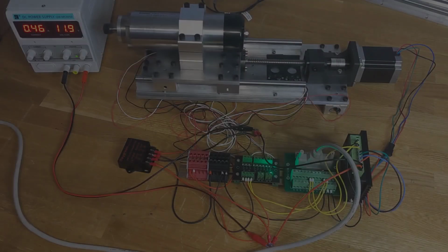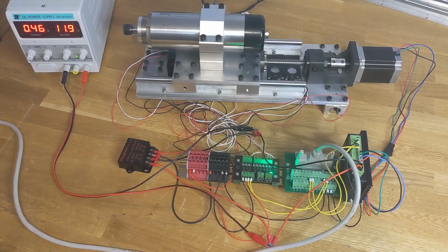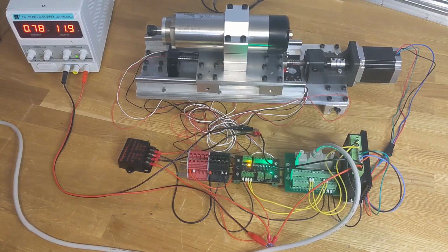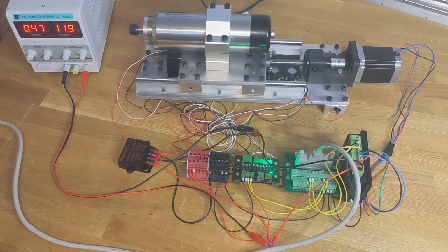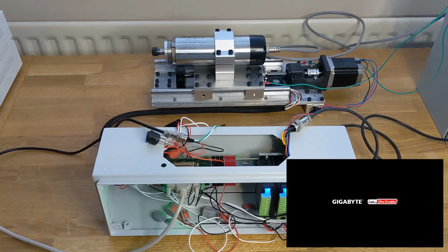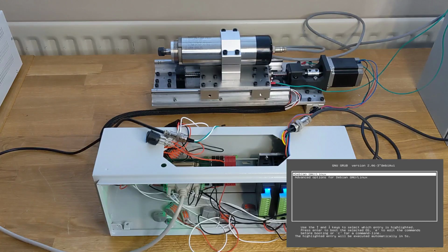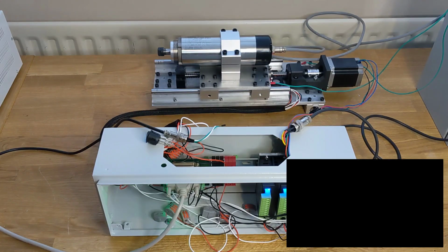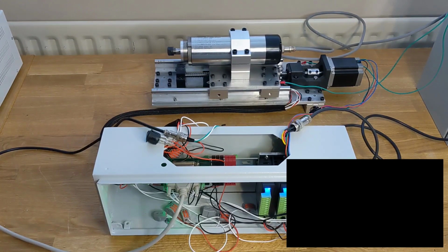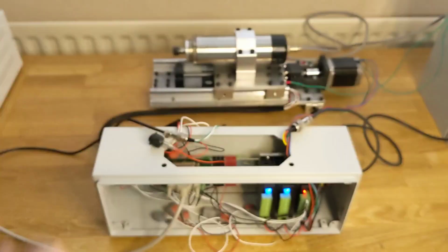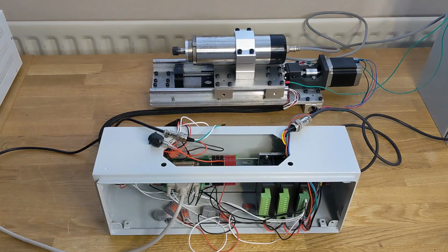In the last video, we set up limits and homing for the LinuxCNC machine. As long as LinuxCNC is in control, then we expect that the machine can't hit its mechanical limits. However, watch what happens when I boot up the computer. Random movements? That's not what we want. Oh dear, I wasn't even expecting that. I actually briefly forgot which switch turns off the motor driver here.